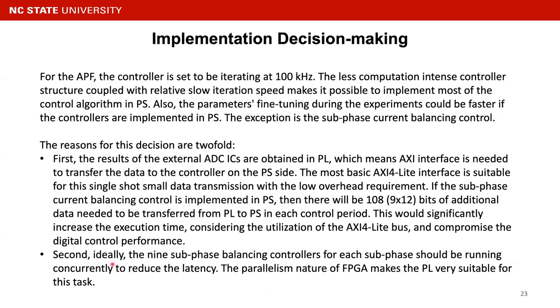Secondly, ideally, the subphase current balancing controller for each subphase should be running concurrently to reduce the latency. The parallelism nature of the FPGA makes the PL very suitable for this kind of task.